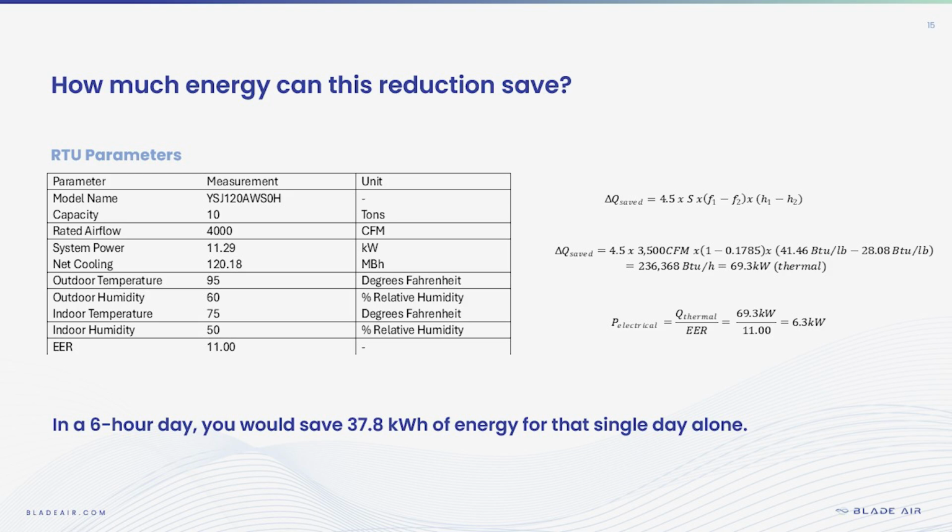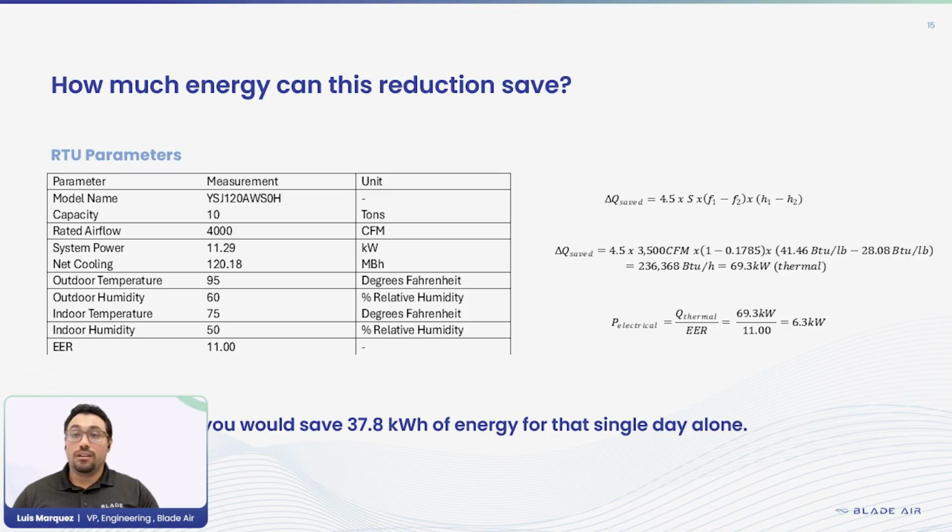I already mentioned we'll assume a really, really hot day and what we want in our indoor standard air: 24 degrees Celsius or 75 degrees Fahrenheit and 50% humidity. So using our thermal energy loss in the first equation, and then calculating for the sensible and the latent heating shown in the second equation.